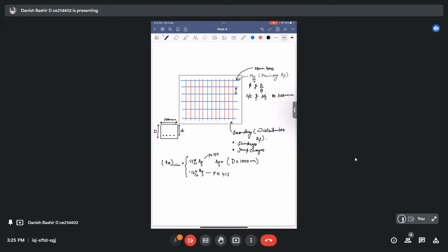So when we remove our formwork, a lot of air cavities, or honeycombing, will be formed in our slab section, and we do not allow that because it reduces our strength very significantly. This is the main fundamental reason why we have a limit on the spacing.